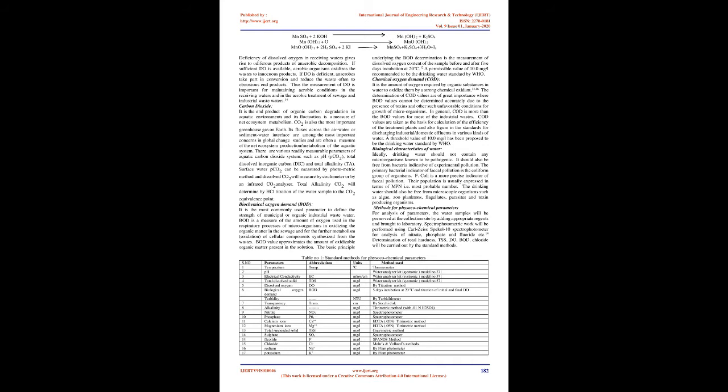The solubility of oxygen depends upon temperature, salinity, water movements etc. Dissolved oxygen in water is essential to aquatic life. DO is the most important factor in determining whether aerobic or anaerobic organisms carry out biological changes. The estimation of DO is done by the titrimetric method. The oxygen of the water combines with manganese hydroxide which on acidification liberates iodine equivalent to that of oxygen fixed.